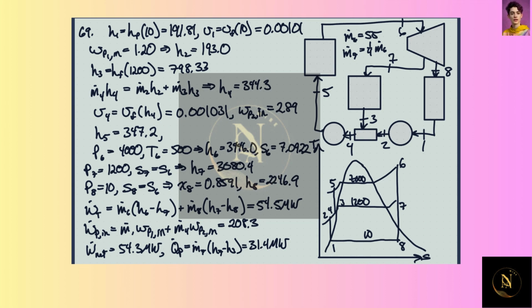So yeah, we have a boiler here, a turbine, condenser, pump, a mixing chamber, a second pump, and then this is a process heater. So this is kind of the new thing with the cogeneration plant. So in this case, let me actually put some energy flow. Here we're taking energy out of the condenser, out of the turbine, and out of the process heater, and we're putting energy into the boiler.